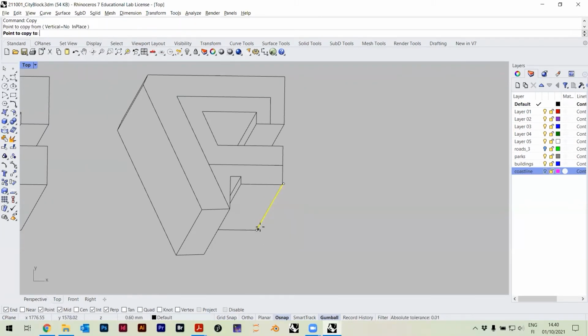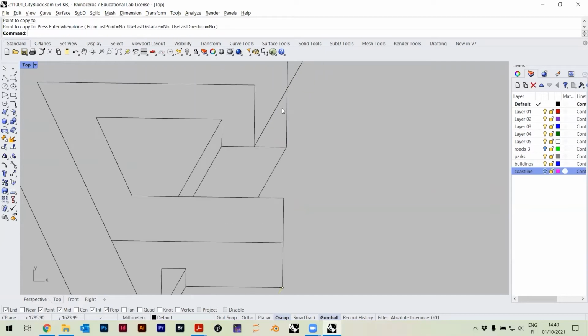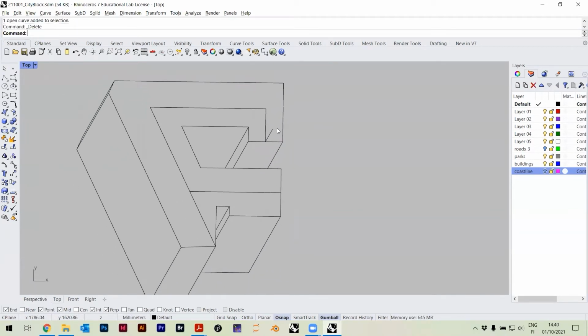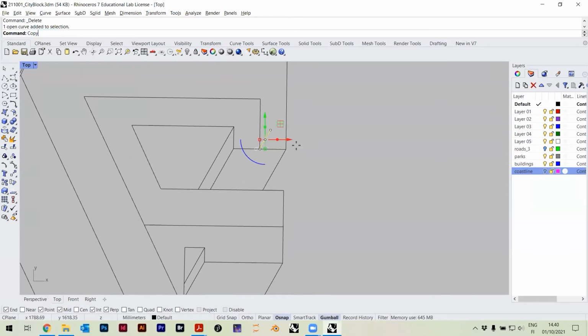I can just copy and extrude here, and then I have to make a decision how big my roof is. So you can use the command called split, which enables you to click on a point. You can just find a point somewhere here and split that line. Maybe the roof is not too high, maybe I split it here. Perfect. I can just delete this part. Okay, this is maybe my roof height.